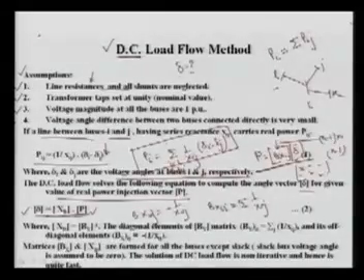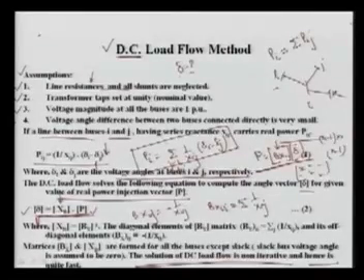So delta can be calculated from the power injections. We know the loads at each bus. We can form this Bx very easily, also during outages and other things, and then we can calculate the delta, and that delta is used here to calculate the power flow. So this is basically the solution. It is non-iterative, and hence it is quite fast. Let us see an example first; I will discuss that example.